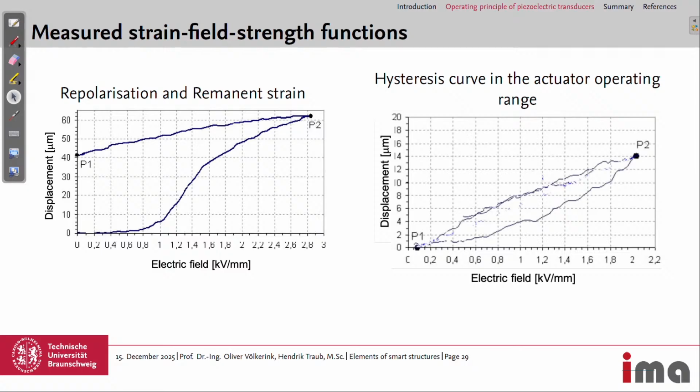Like you have mentioned that we require at least 2 kilovolts per mm for the poling. So doesn't it depend upon the thickness of the material also? Yeah, sure. If the electrodes are further away, then you need a higher voltage.